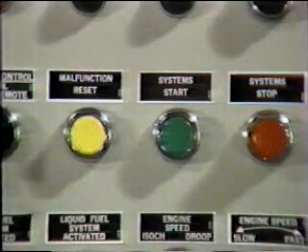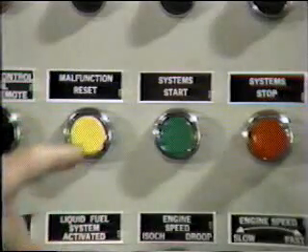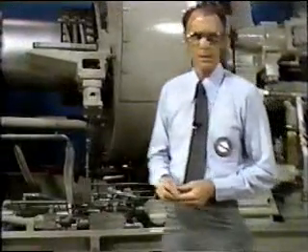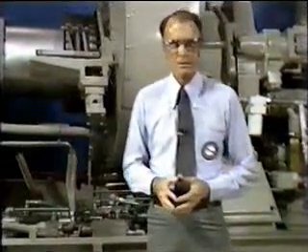of events during the startup cycle is controlled by the DC system. A variety of switches, timers, monitors, and other devices are used to sequence and activate the components of the fuel, start, and generator systems. Now, you may already be familiar with, for instance, the start switch S101, the prelude timer KT222 located inside the console, and, as an example, another item of hardware that's controlled here, the electro-hydraulic actuator on the package. Now, they are part of the controls for the start sequence.